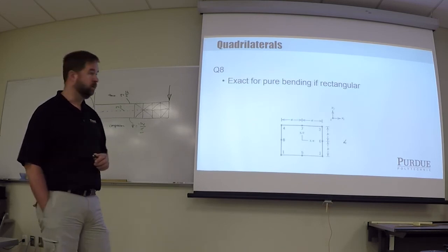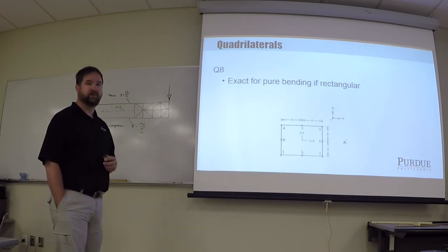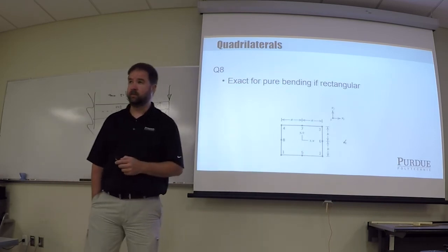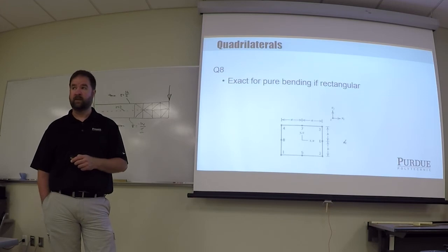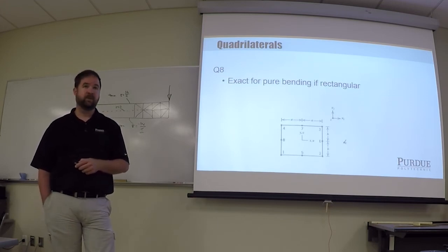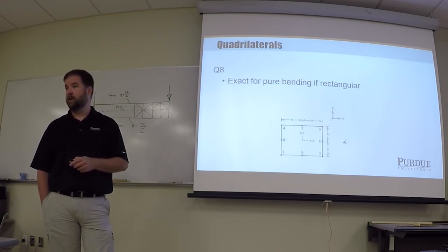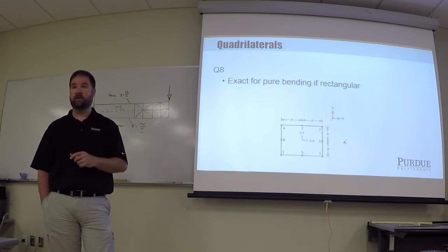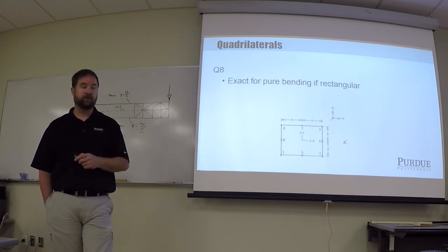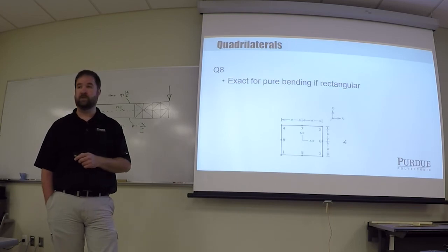But other programs, I think I've told you already, there are finite element programs that are only finite element programs. For example, that would be ANSYS. They're a higher end FEA. You can choose between triangle elements and quadrilateral elements. Quadrilateral elements will generally give you better results.